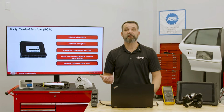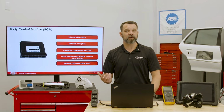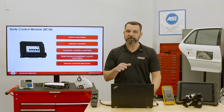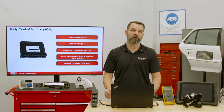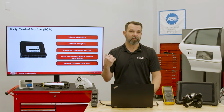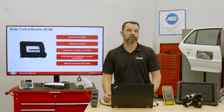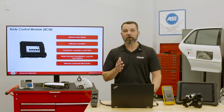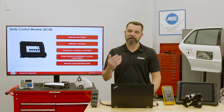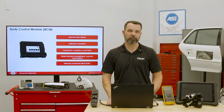So some quick diagnostic tips here. Always check the BCM DTCs first. With these newer vehicles that are on the road, we're getting a lot more data and functionality through these modules, so it's likely you'll find codes that might actually lead you to a good starting point in your diagnosis. If you can, watch live data to see if the body control module is actually receiving the switch inputs, or you can use bidirectional controls to command the actuators. Also check grounds, because body control modules are extremely ground dependent. And as usual, if you can, inspect for water entry, especially below the dashboards.